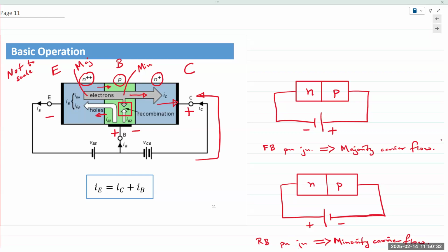And so I like to state it as you have this DC voltage applied between your two terminals, whether it's the gate and the drain and source, whether it's the collector and emitter, and then you take your AC signal. That AC signal, the device is going to give the shape of the AC signal to this DC voltage that you're applying. Does that make sense? And that's how we get the amplifying effect.